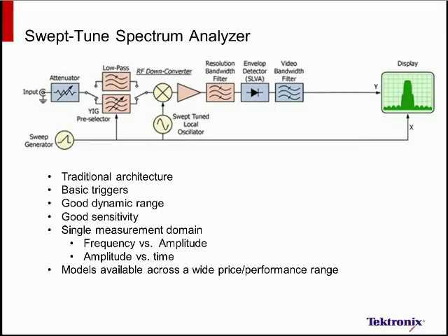So let's look at a swept-tuned spectrum analyzer. Swept-tuned spectrum analyzers have been around a long time. We call this a traditional architecture. In a swept-tuned analyzer, we know that we have low frequency on the left, high frequency on the right, and power logarithmically on the y-axis. In general, we get good dynamic range and good sensitivity, but we have two measurements we can make. We can make frequency versus amplitude and amplitude versus time.